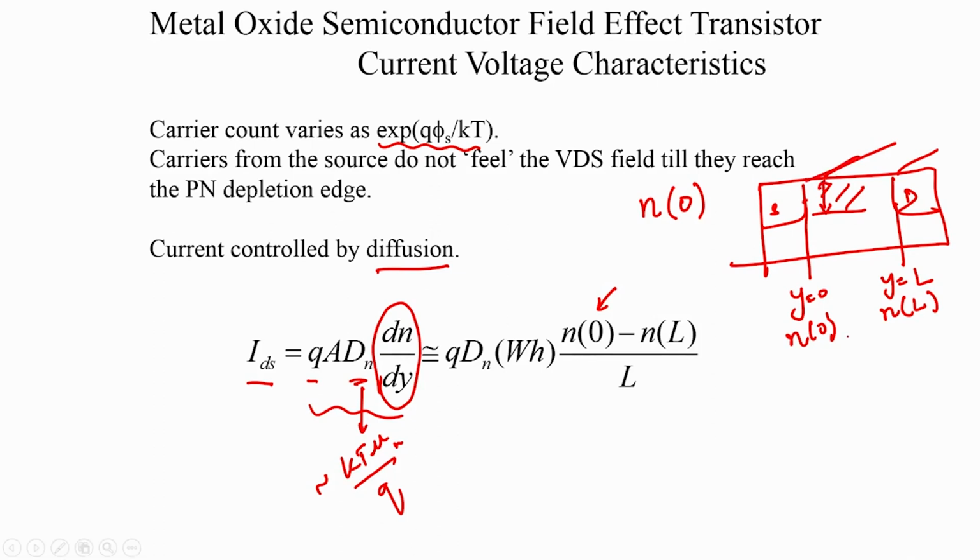So the last time while performing the analysis on inversion, we said let us treat all the electrons like a particle, and this sheet of electron charge had a thickness of h. Now we never defined h, because h cancelled off, but here let us retain it and we will try to get an approximate estimate of what h is. So this will constitute the area of cross section, which is the channel width into this thickness h.